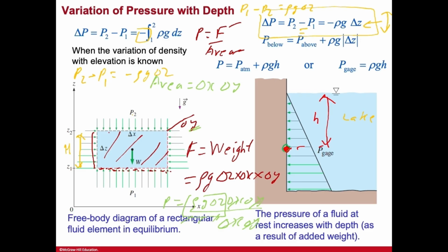So the pressure acting on this point will be the pressure because of the liquid column or water column h. So that is going to be rho gh, but there is also air above it, right? It's not vacuum, you have atmosphere above it. So the atmosphere also provides a pressure. So that exerts a pressure. So the pressure at this face, or at the sea level, is atmospheric pressure, and you have to add that pressure to find the final pressure at this point, right?